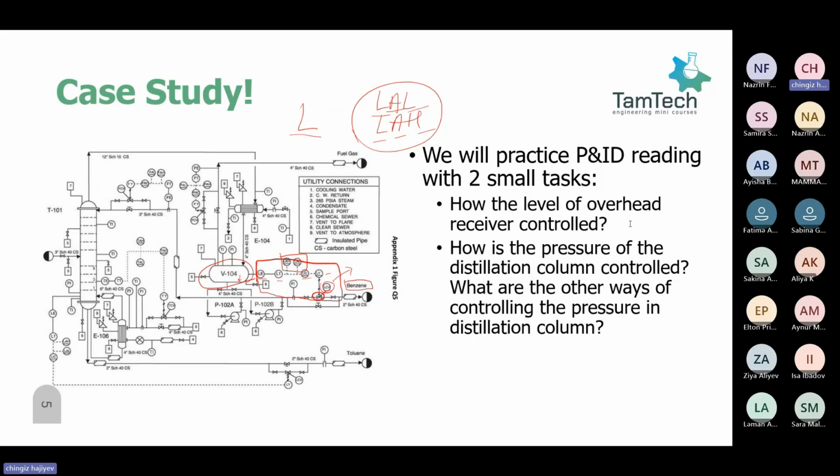It just compares and sends a signal to the action element. What measures is this LE here, and the transmitter sends the signal to our controller. Measurement is done within the control loop, but not in the controller. It's other equipment. Okay, I guess we're done with the first question.